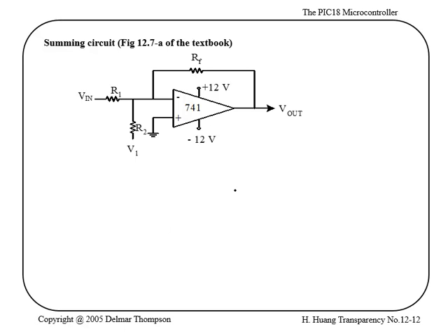There's going to be summing circuits. So this is a sum circuit, and assuming that there is no current going to go in here or on this pin, if this is grounded, then this essentially means that at this point you have 0 volts. Right?